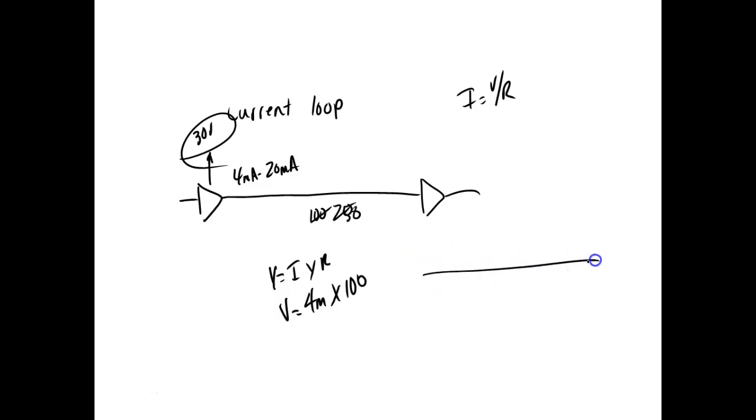Originally, when we sent voltage signals, we would establish a common and send the signal down the wire. The common was also a reference to ground. When voltage came through this, it would generate a pulse into that, but it can't generate a pulse in the ground because that's what it's referenced to, right? So we would shield this, run copper wire around it, shield it the best we could if we wanted to use voltage.